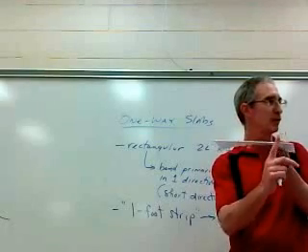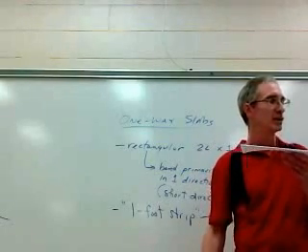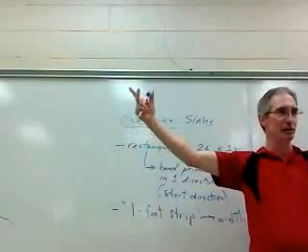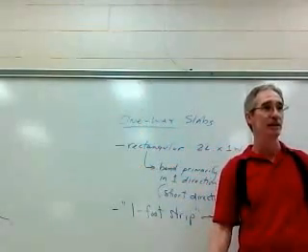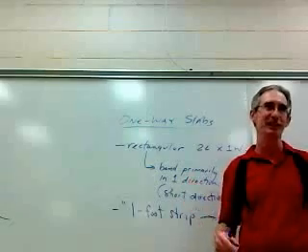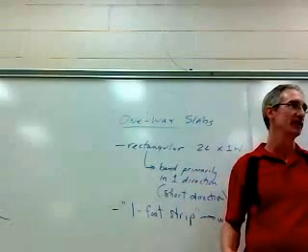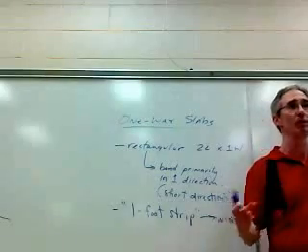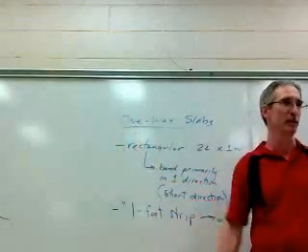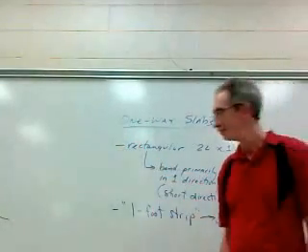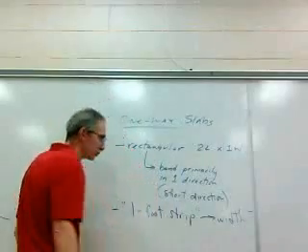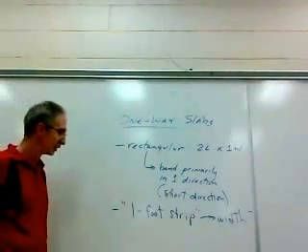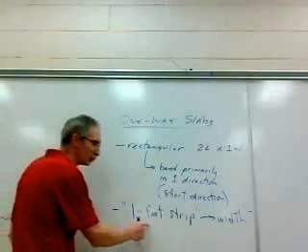It's the same as this 1 foot strip from there to there. So most people will say, even though you have this slab that's 20 feet wide by 5 feet long, let's just look at it like it's 1 foot wide. And then we'll design or evaluate it in this 1 foot strip, and all the other strips will be the same. Okay? So a 1 foot strip is typically going to be our width. Our width is typically 12 inches.